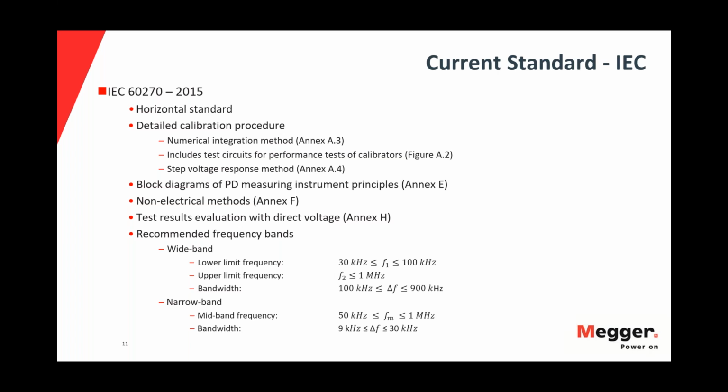With 1 megahertz you can cover the whole area of the object under test, but keep in mind that at that range there is also more noise. As you increase the frequency, there is less noise, but you cover only a localized area. Each frequency has benefits, and that's why we provide both.